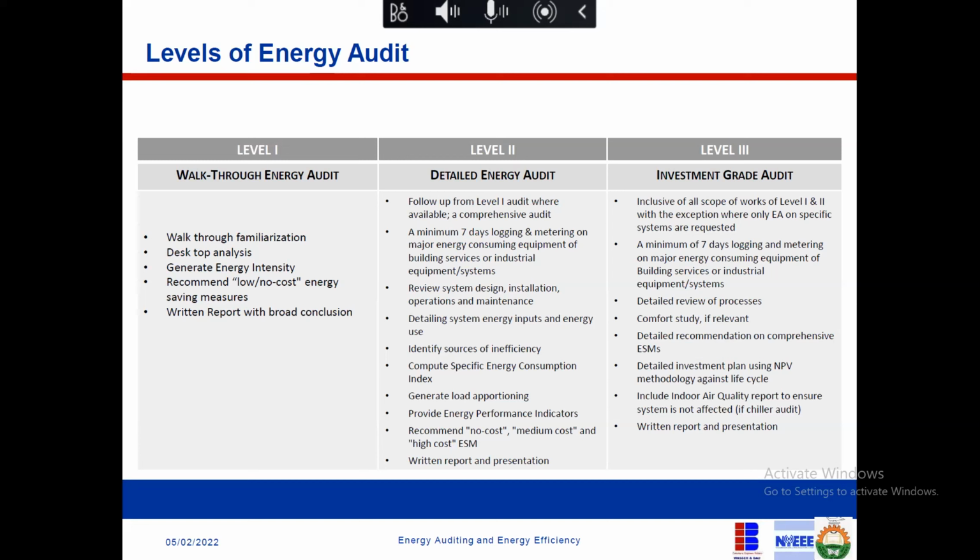Do you know I have to go to my effluent and take data of the analysis, the nitrogen concentration, the phosphate concentration, the BOD concentration, the COD concentration, because that will give me an idea of the level of the energy input and the level of treatment, because it is garbage in, garbage out.